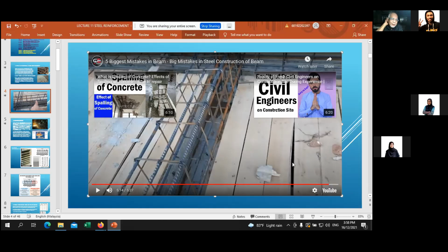Use formwork, I mean, plank like this. In Malaysia, they use plywood, or they use metal formwork. So you don't have this kind of opening. This opening has to be sealed off, if not, there'll be some bleeding, concrete bleeding. Material that is possible to do it, probably quality is a bit different from here.